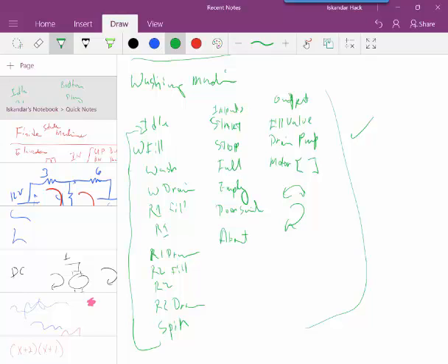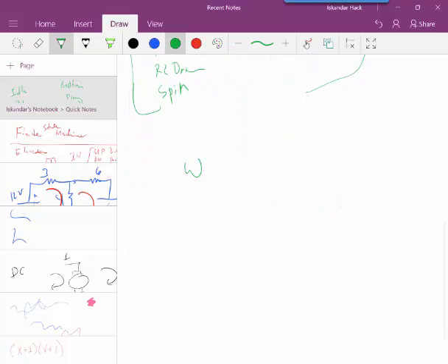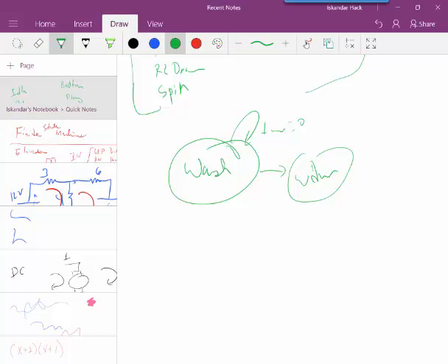Again, when we look at a particular mode, say we're in the wash state. Here's our wash state. We're going to stay here until our timer is equal to 0. In other words, it's counting down. Actually, we just have a delay there. And we go from wash to wash drain. And we stay in drain until empty is equal to 0, in other words, it's not empty.